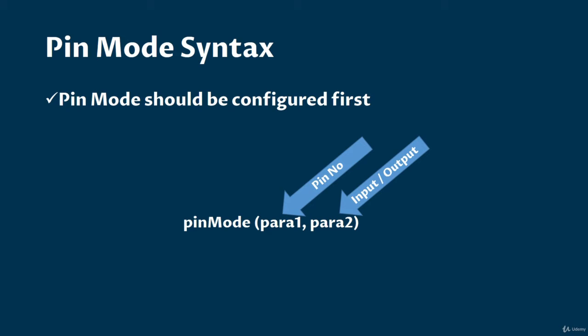As a sample, say we want to define pin 9 as output. Then how will we write that? So we can write pinMode within brackets 9, comma, OUTPUT, all in caps. Here pin 9 will be giving voltages. That's it. Now similarly, the digitalWrite function is like pinMode.